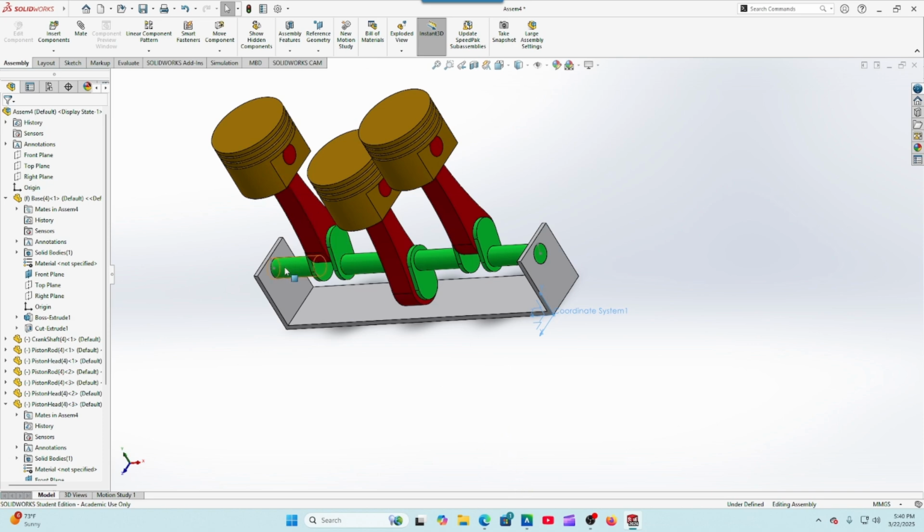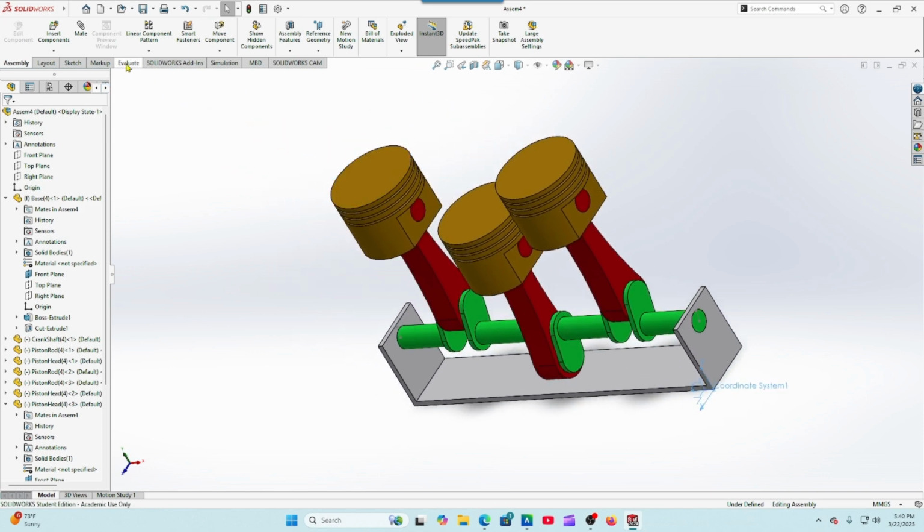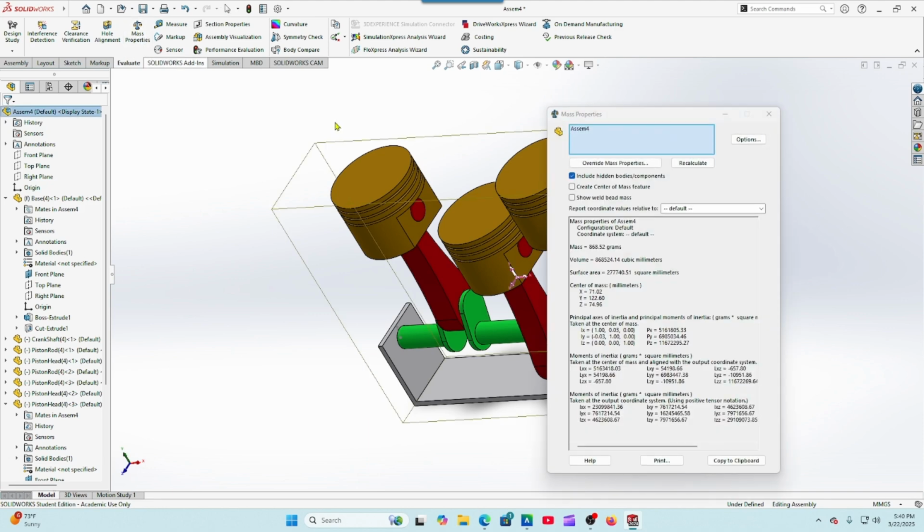And let's go ahead and see what we wind up with in our mass properties. So here you want to make sure that you select the coordinate system that you put in. And right now I can tell you that something is wrong with this based off of what we have right here. The X equals negative 28.